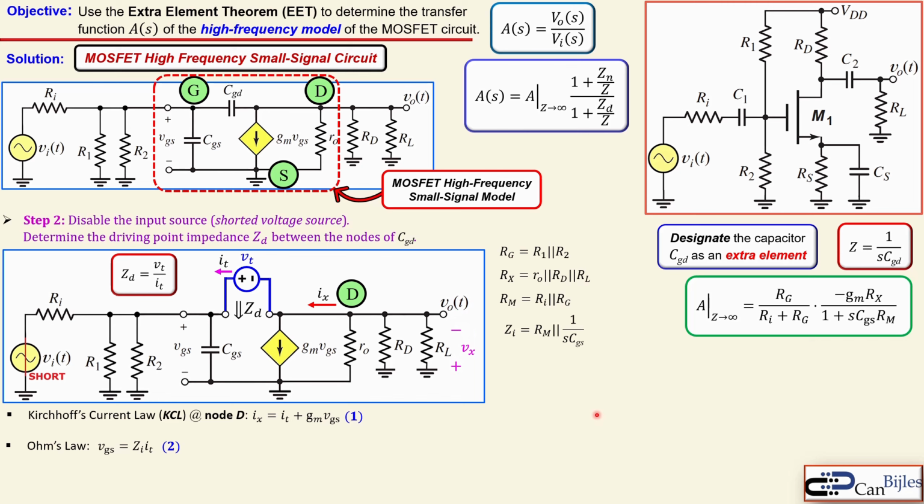Now the next one is about the voltage here. That is what I will designate, which is exactly as VO, of course, on the opposite sign, but it will be helpful to make it in this polarity because the current is going in that direction, just convenience, not really required. Then I have here the Vx, which is then oriented like so. And I have now an expression, I can say again using Ohm's law, that Vx is this complete resistance Rx, which is the parallel combination of these 3 components, times the Ix, which is going here.